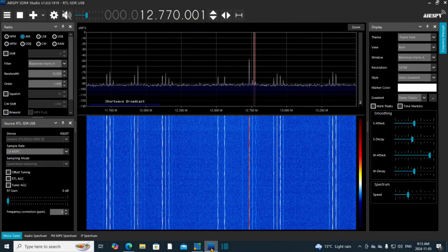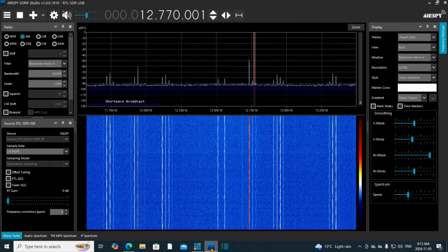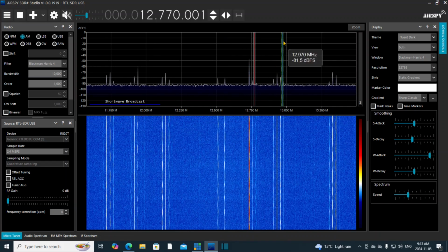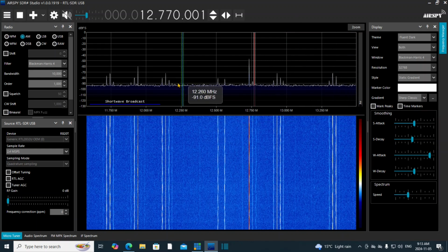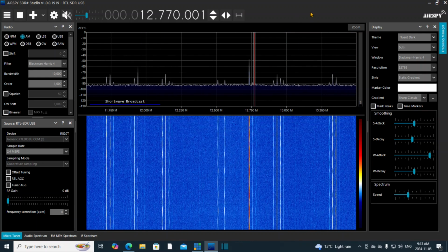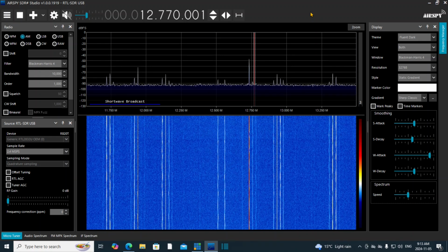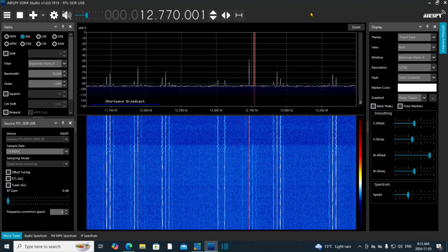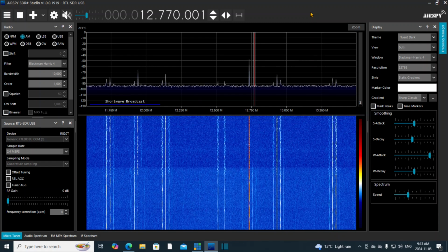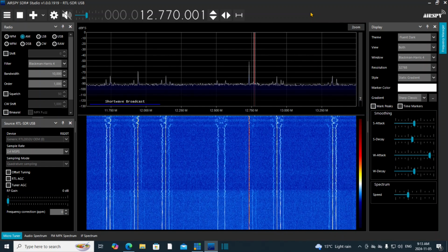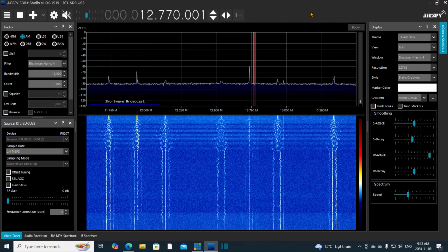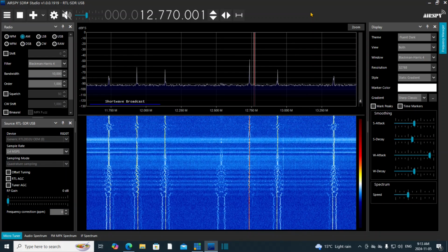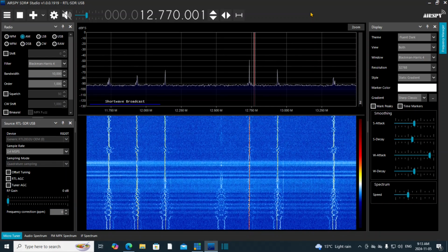Okay, so here's the SDR, and it's tuned to the same range as the radio, and you can see this large signal right here. That is the local oscillator, and all these other things are bizarre artifacts coming from either the SDR itself, perhaps from being overloaded, which I don't think is the case right now, or it's coming out of the radio. So that's a local oscillator. Why is it jumping like that? So I'm kind of swinging the radio back and forth, so maybe we got something a little loose here. Don't know exactly why it's doing that.